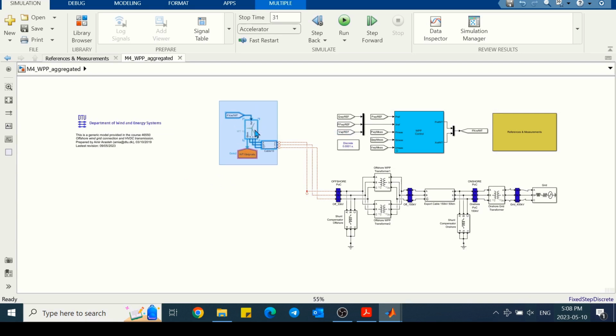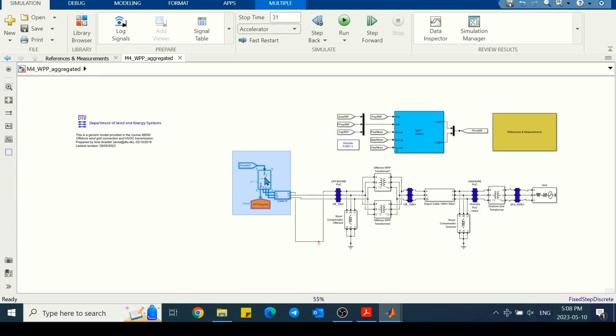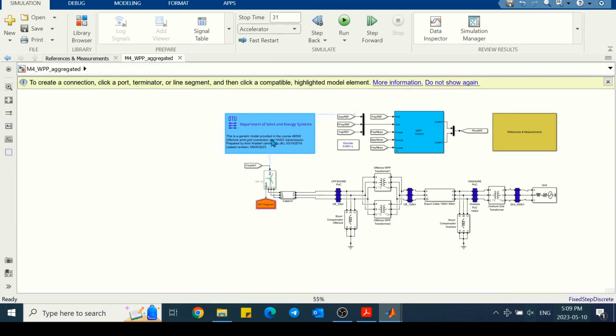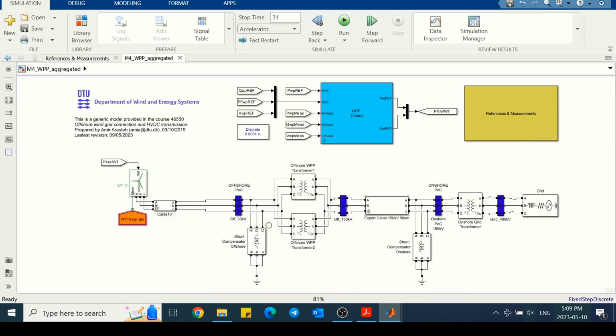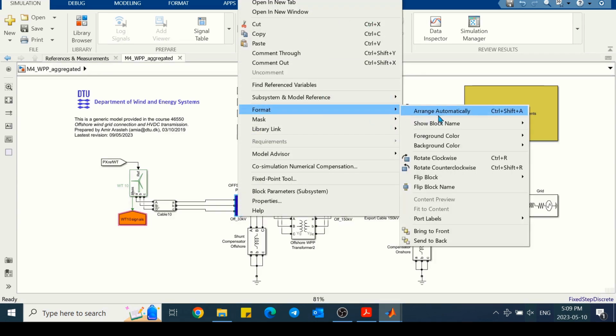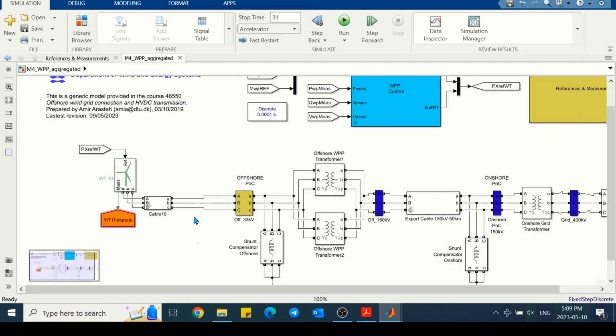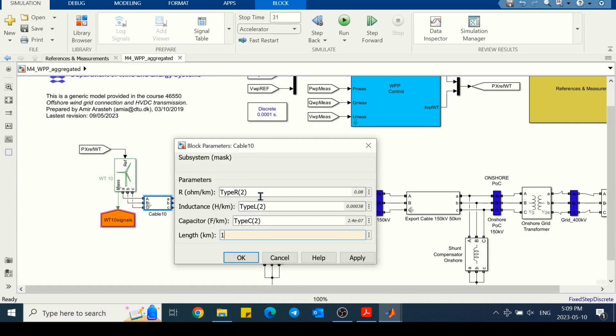When doing this connection and modification, the most common mistake that might happen is the phase connection. So just make sure that all the phases are connected to the same phase in the three-phase system. Let's change the background color of this measurement block to yellow, so it's easier to see the label of the ports. If we look, we can see that all the phases are connected accordingly.